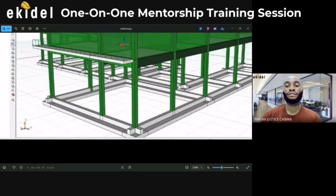You can see that. So they're asking you, what's this distance? That's what they're asking. Exactly. So it can be 1 meter or 1.5 or 2 meters. So the more the cantilever length, the wider the footing. The footing under the beam will be wider. Yeah, so that's what they're asking.